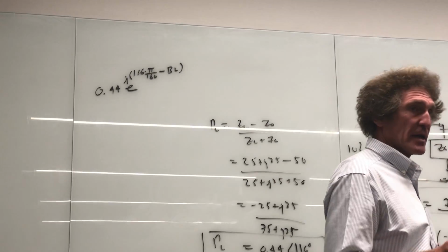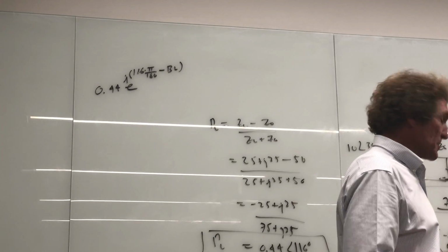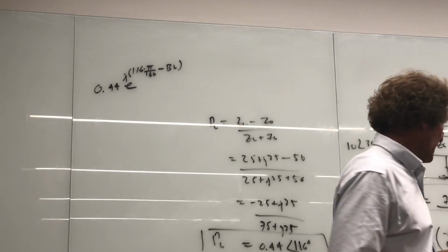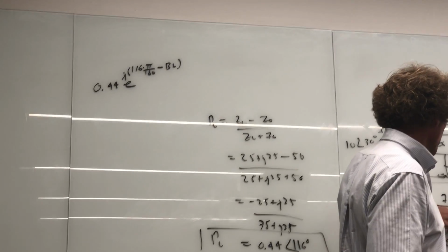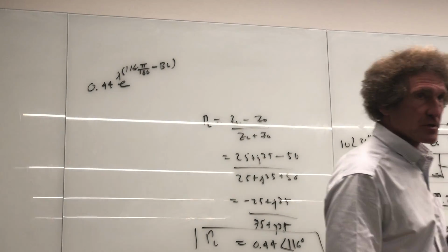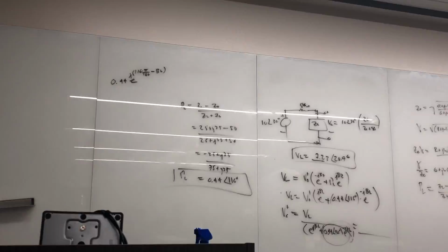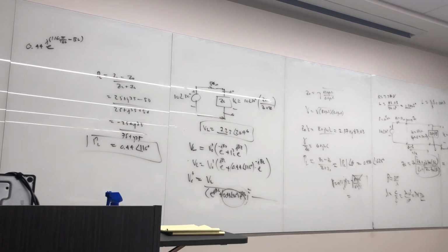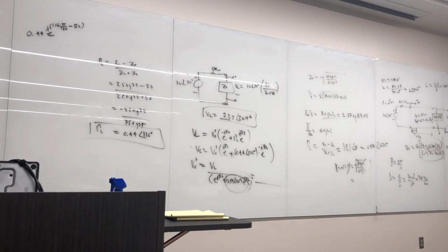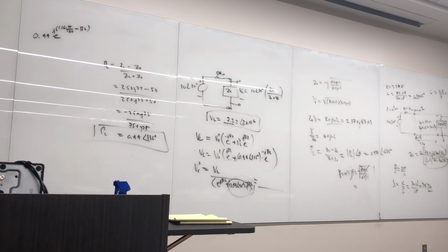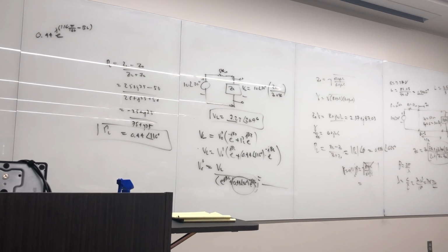You can stick that right in there and add it to just j beta L. And then add those two together, then divide it into VL. And VL is this. You should be able to do this efficiently. But I think I'm exposing some of the clumsiness, because on quizzes and stuff, they're about 10 minutes. And this is a typical quiz problem. Very typical.